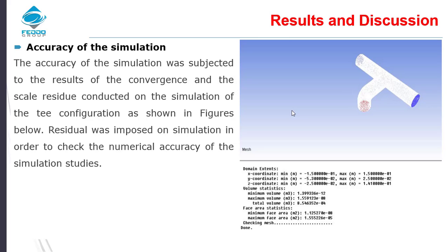When dealing with CFD codes, there are three important aspects to abide by for iterative convergence. First, all the discretized equations, such as momentum, energy, etc., are deemed to be converged when they reach a specified tolerance at every nodal location. When I talk about nodal, I mean the node and element. When you are talking about the discretized, that's the meshing part. Now you have different meshing sizes, then you talk about the nodes and the elements too.